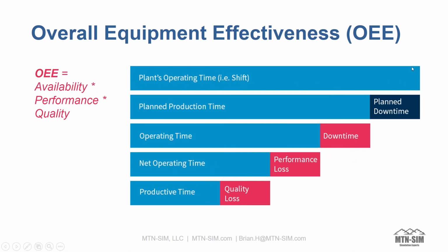First pass yield. So this is switching gears over to a little bit of our quality side. First pass yield is a good metric that just keeps track of the number of parts that have passed through a particular workstation, and we're going to keep track of how many of them were good, the number of them that were scrapped, and also the number that actually were reworked.